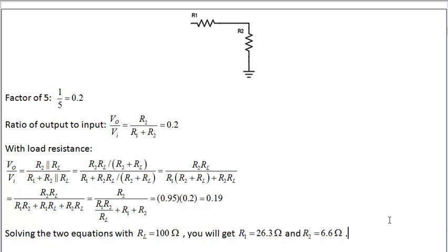Now a great concept question to do from here is to think about how the size of the resistors mattered. So yeah, we've got these specific numbers, but what does that mean? If you use higher resistors, then what does that do to the output? Does it mean that there's more droop or less droop? If there's less droop, then for whatever resistor direction, what's the trade-off for that? Because wouldn't you want to just make a voltage divider that has the lowest amount of droop possible? Well, as usual, there's a design trade-off. So see if you can solve that on your own. And once you're done, we'll pick it up right here.